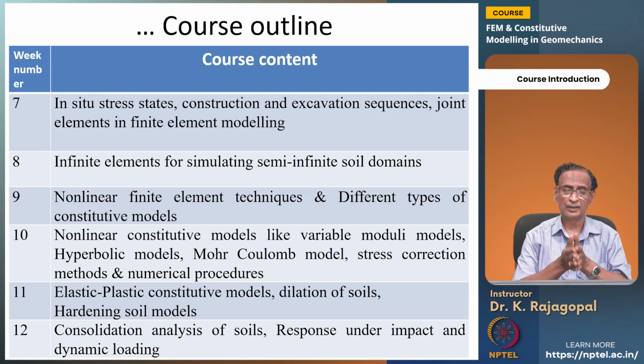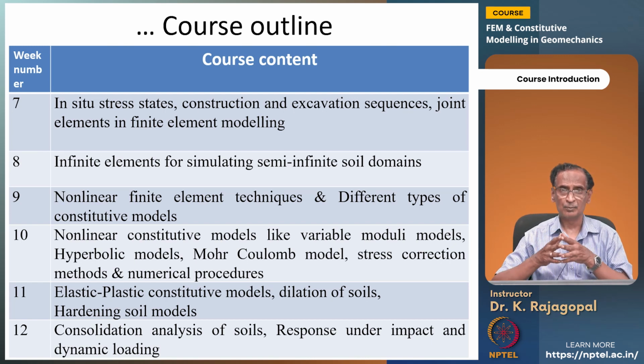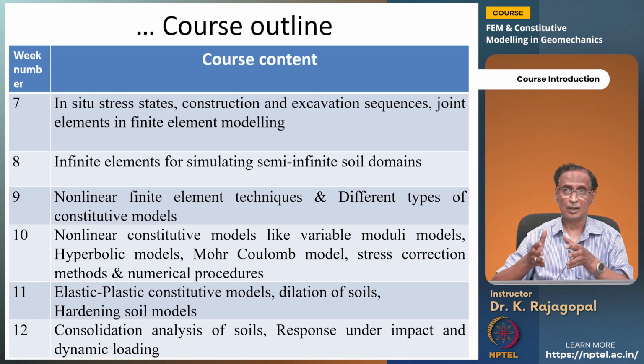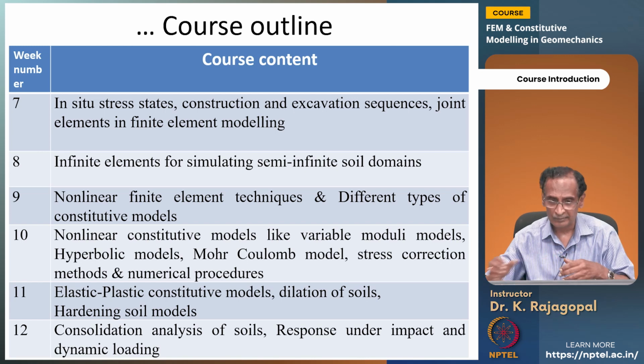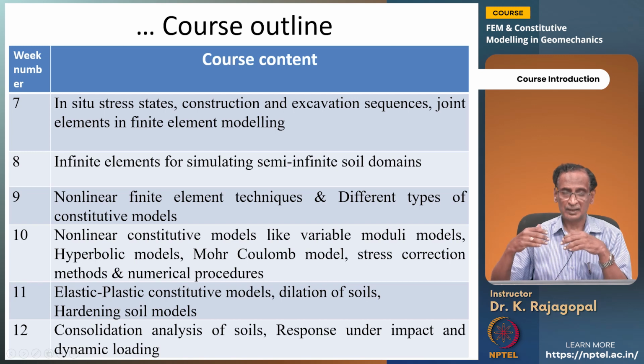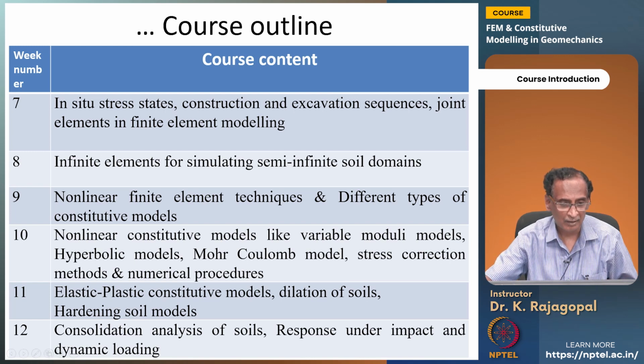But then how do we do that in finite element analysis? Especially our computers do not like the word infinity. They will just simply crash. They cannot accommodate this infinity. So, we need to look at some special elements that are called infinite elements or mapped infinite type elements that are specially developed for taking care of this infinite soil mass. And then we will be moving on to our